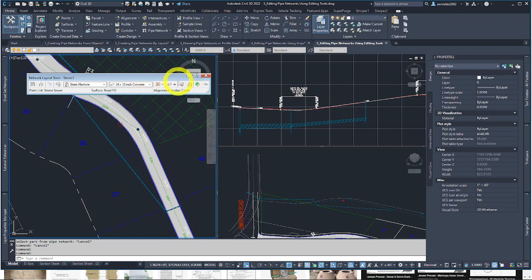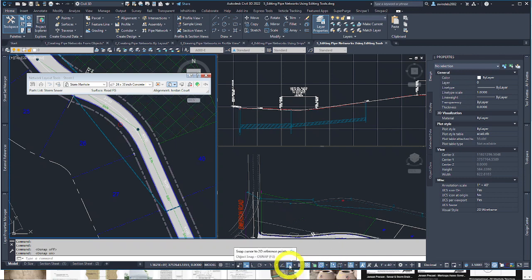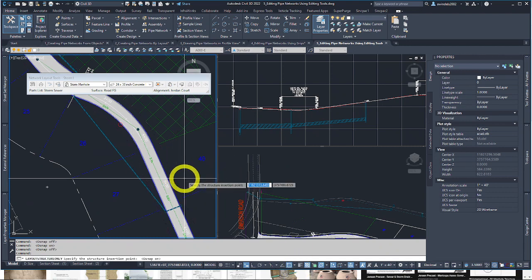So great. Now we're going to look for the black triangle to the right of this pipe drop down list, and we're going to say we want structures only. So this is saying we're going to insert structures or pipes or both, depending on what we have selected here, which pipe and which structure. Okay. In this case, we're going to say structures. Make sure your OSNAP is now turned off. You can click it here or hit F3, which is my old personal favorite. Nothing is really cooperating here for me. AutoCAD is awesomely fast sometimes. Hit F3. That did it. Okay.